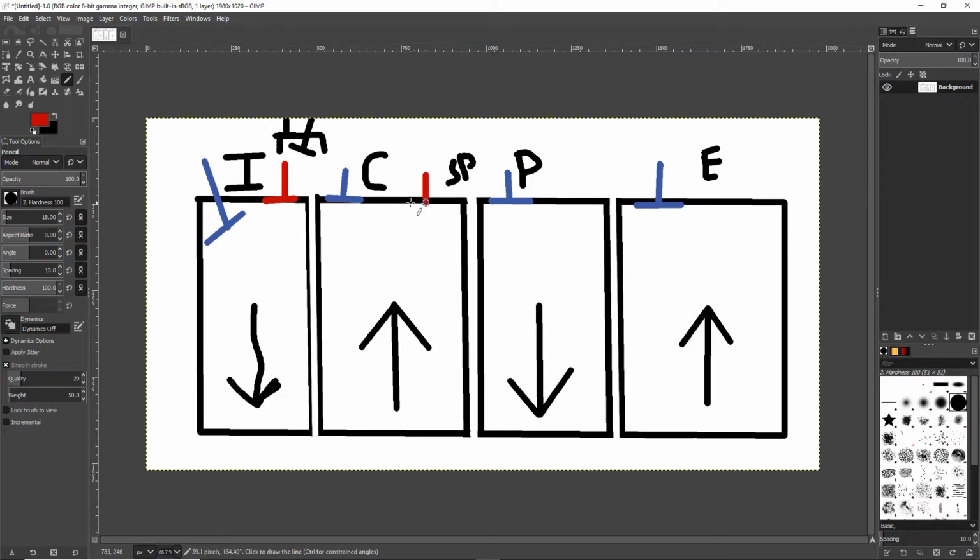When I go to compress it, I don't want anybody open. Don't do that, it would leave. I want to squeeze it, compress it. On the power stroke, I don't want anybody open. Don't leave. I need that burning to push this piston down. And then finally, when I get to the exhaust stroke, that's when I'll open this exhaust valve. Okay?